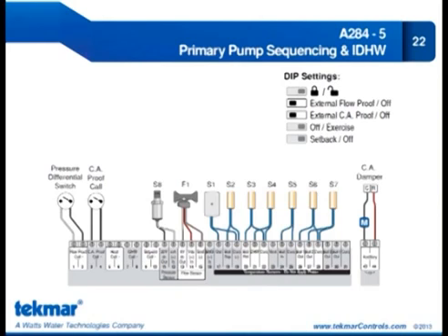So in the case of combustion air, the operation is basically the same as with existing products, such that we will turn on that contact prior to boiler operation. But once you turn it on, if you have a proof selected, then we'll have to receive that proof before we allow the boiler plant to be staged on. So that operation is consistent with existing products.